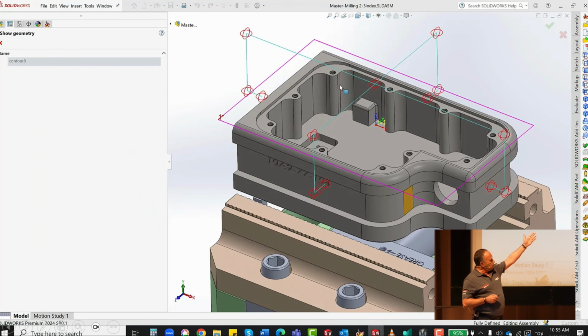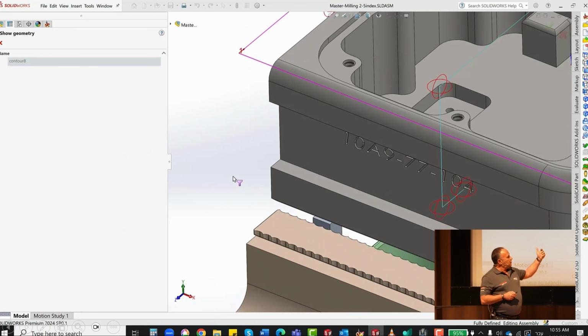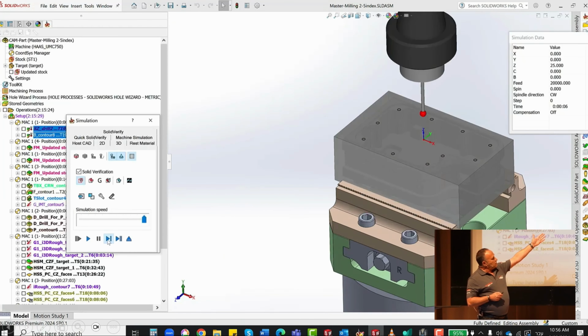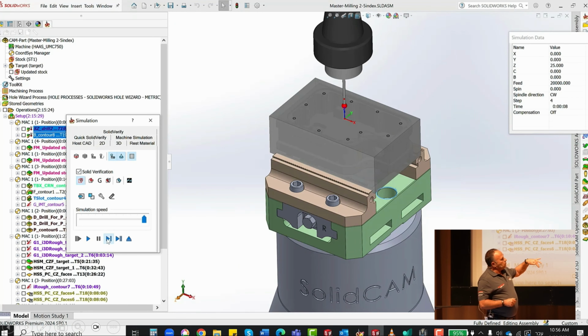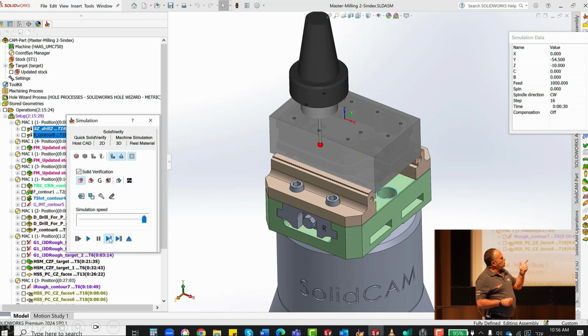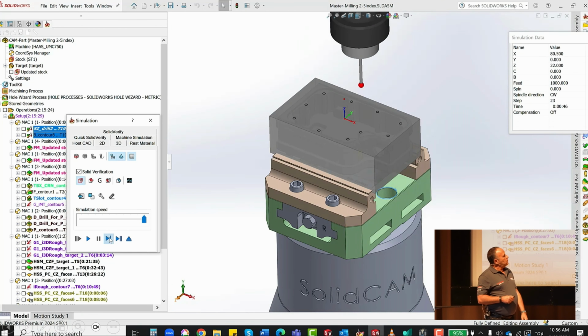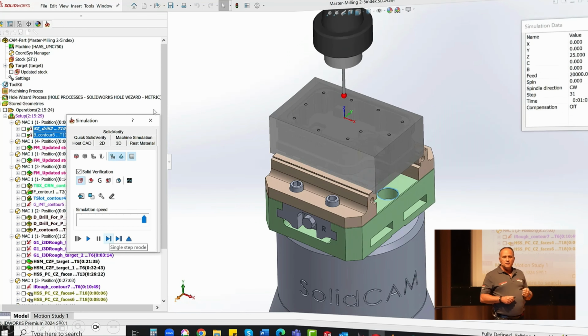If we select the boss option, then we need to define it, and automatically the system gives us 4 points to touch. And as you can see now, we touch the material, transmit the Z-axis, and after that, touch 4 points and send the center of the material directly to the controller.